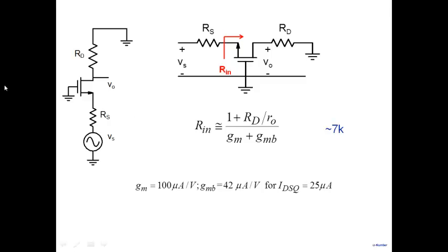All right. So the input resistance for this amplifier then is a problem. And you note that one of the major advantages of a MOS amplifier is that MOS offers you infinite input impedance. And now when you use a common gate amplifier, it's giving you an input impedance of only 7K. So that's a very negative feature about this common gate amplifier here.